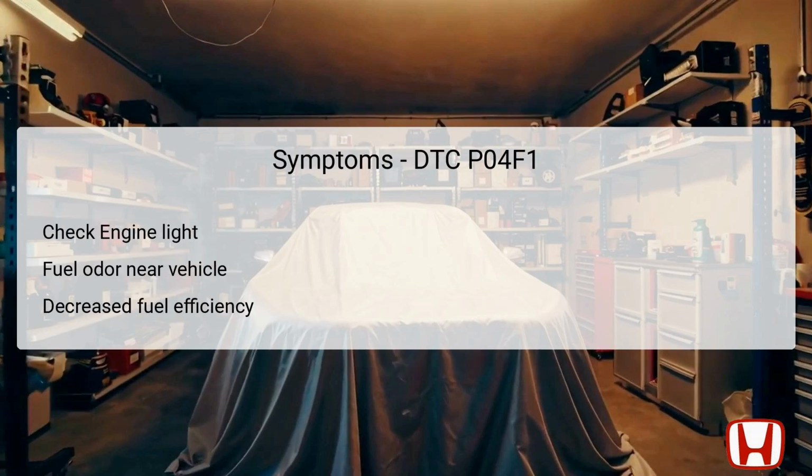Drivers may observe several symptoms associated with DTC P04F1. The most immediate sign is typically the illumination of the check engine light, signaling an emission-related issue. It may also be possible to detect a fuel odor near the vehicle, which may indicate fuel vapors not being captured correctly.